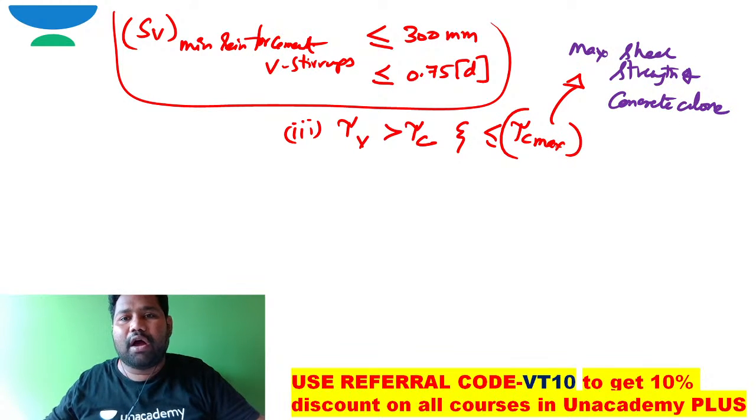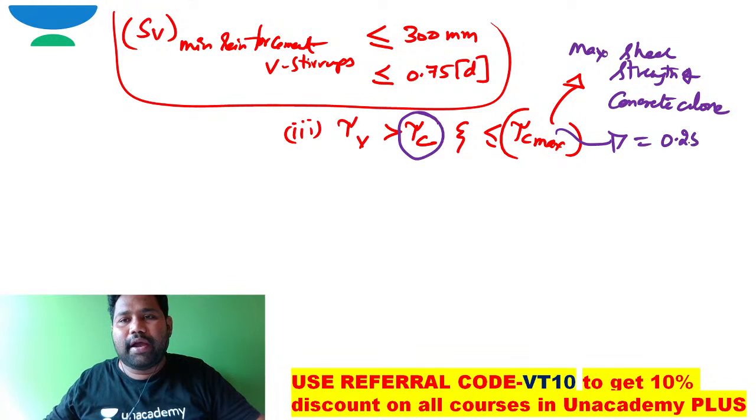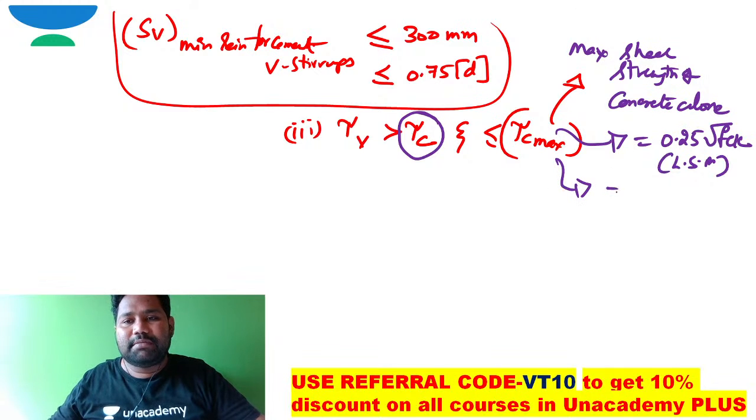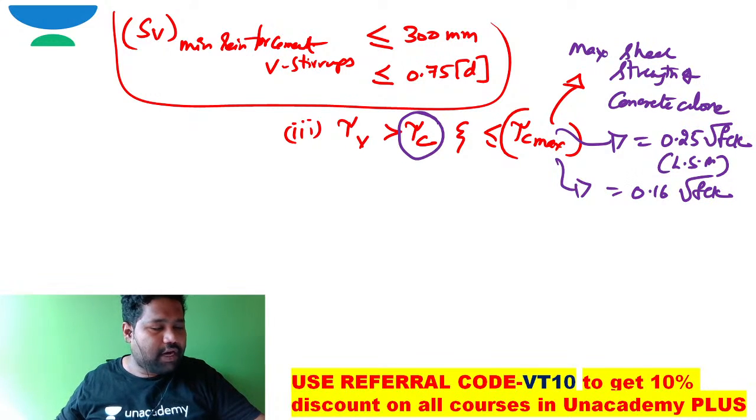Some people will ask how to work out this tau c max. This tau c max we can write as 0.25 times root fck as per the limit state method. As per the working stress method, we can take it as 0.1 times fck.